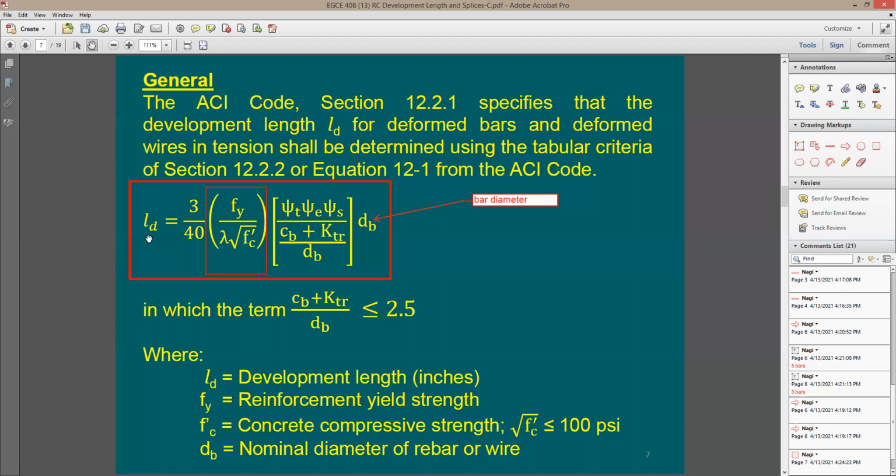Okay, we're going to see the factors. Psi sub s depends on the size of the rebar. So for each rebar, you're going to have a different psi sub s. Just think also about the bond. The bond is based on the surface area of the rebar. So when you take, for example, As divided by the perimeter, or the other way around, the perimeter of any circle divided by the cross-section area, you're going to see that the ratio is usually not constant, because it's based on the diameter.